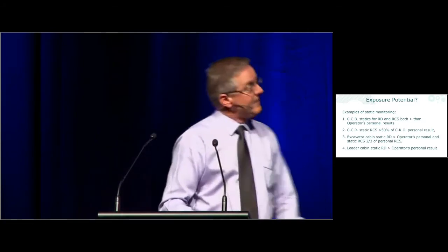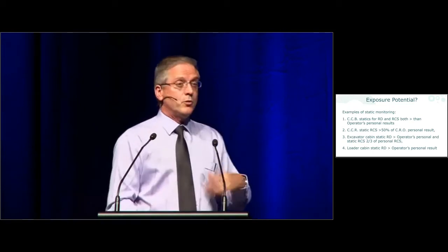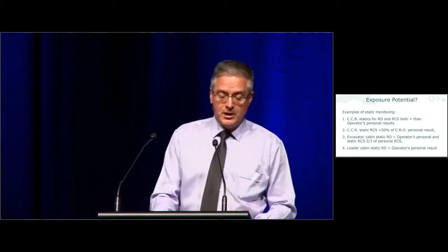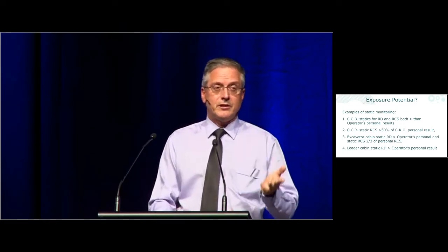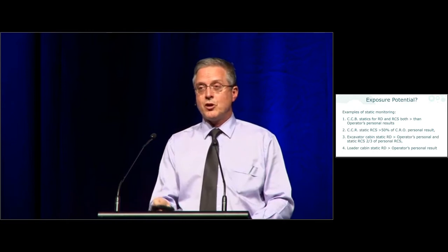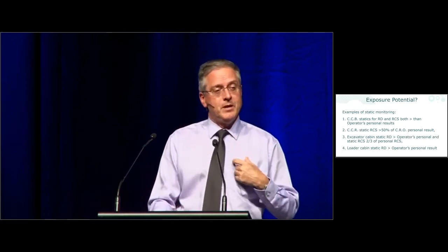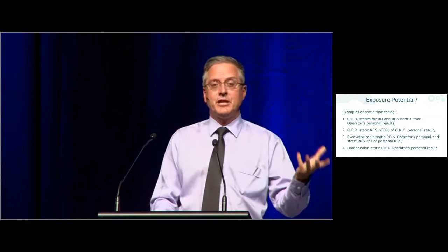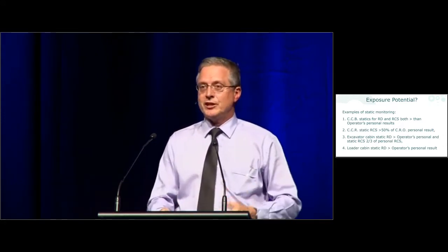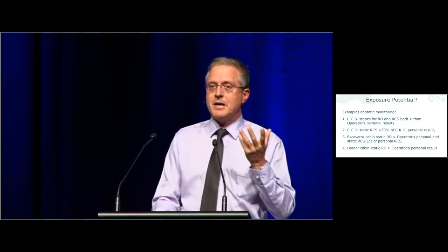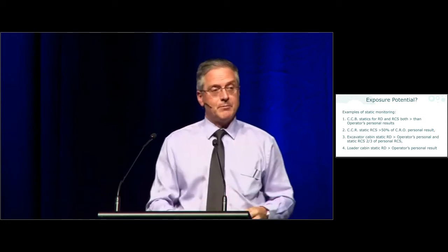Exposure potential again. I was talking before about dust ingress in the cabin, so one of the things that I'm doing when I go out and sample is if I've got a mobile plant operator or a crusher control room operator, I'll put a personal on them and then put a static sampler in the cabin that he's working in. And there's quite a lot of value in static samples when you're looking at whether or not the environment the worker's in is actually controlled, especially given that you won't find any workers who wear dust masks or respiratory protection inside these cabins.